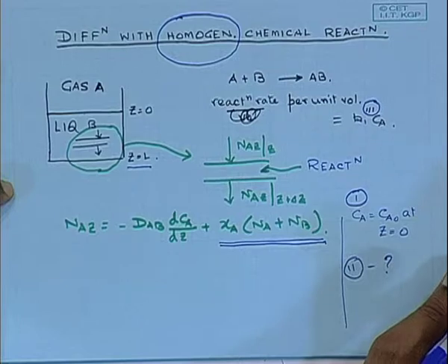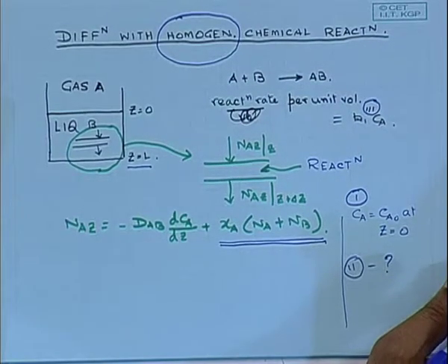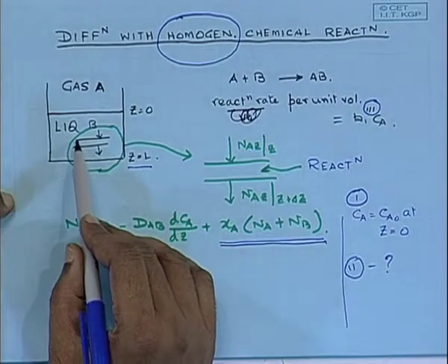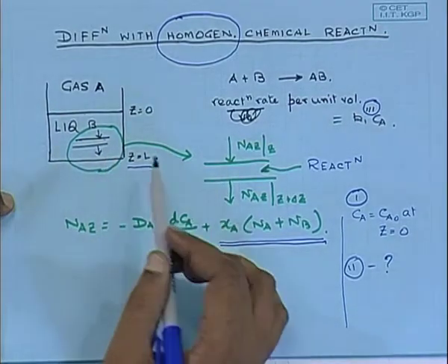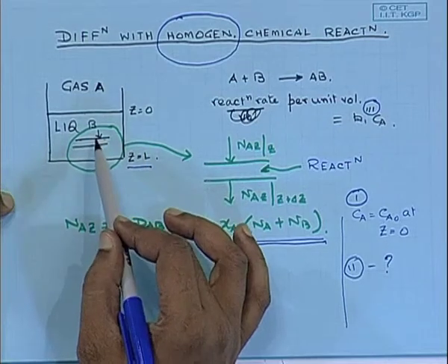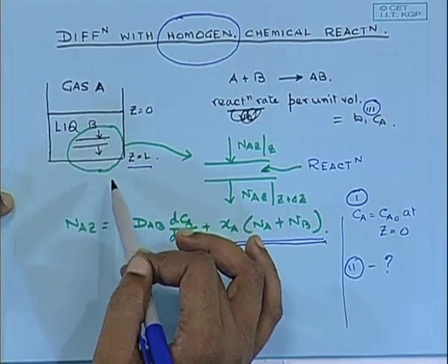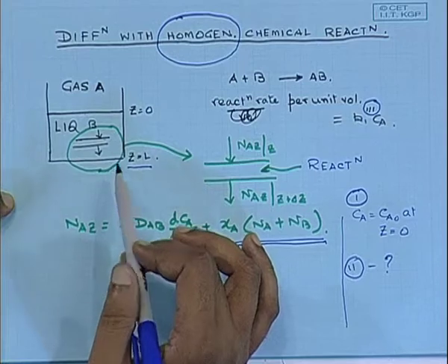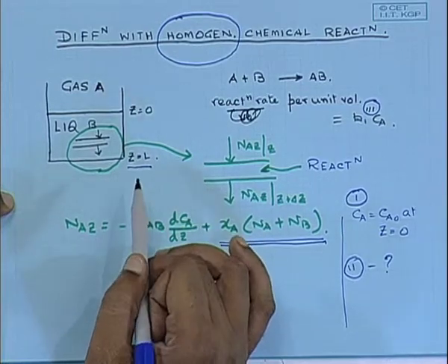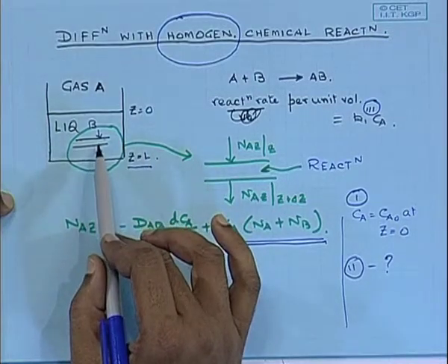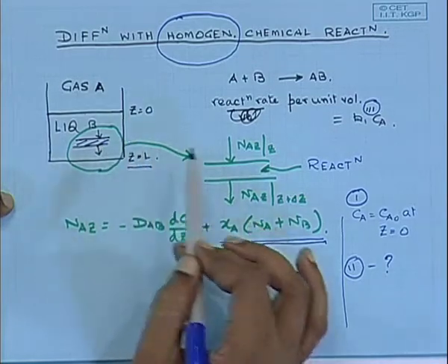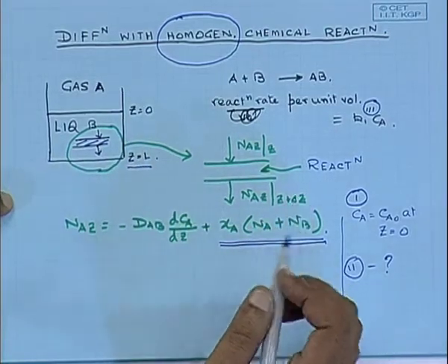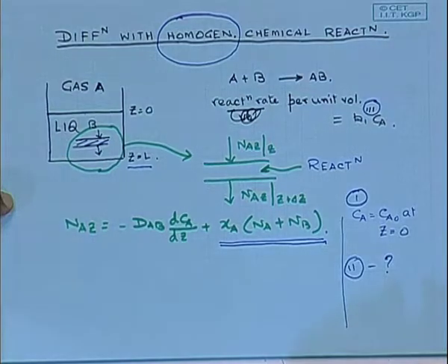So, that is the reaction rate. Now, in order to analyze such a system with shell mass balance, what we can do is take a strip of thickness delta Z and find out all the in and out terms along with any source or sink. Unlike the two problems which we have analyzed previously, in this case we will have to see whether or not any reaction, that means a source or sink term, is present in this control volume.